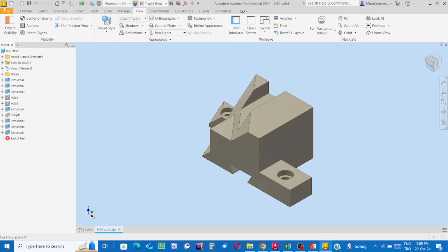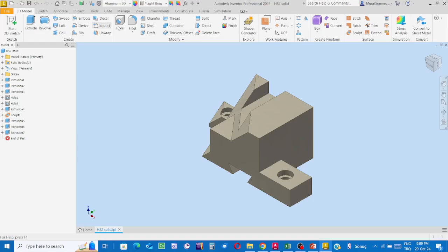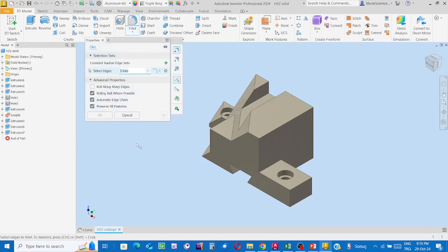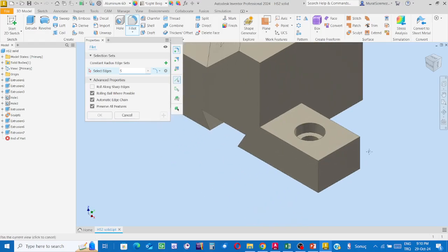Okay, well, round this edge, for instance, this edge. Now I'm using the tools of Inventor, by the way. Click on this button and then write the rounding radius, say that it is 5, into the box. Later we're going to practice on rounds and fillets in Inventor. This is just for the definition part, for demo purpose. Okay, and then indicate this edge. This edge, for instance, at present is a sharp edge. Indicate it, and then you see it is about to be rounded.